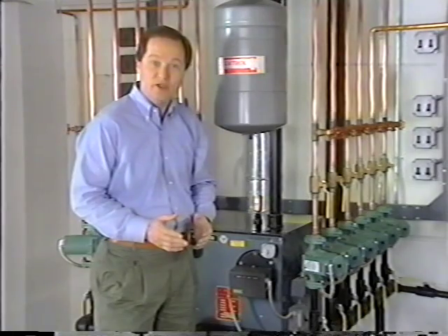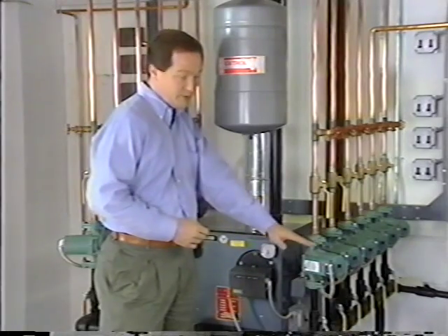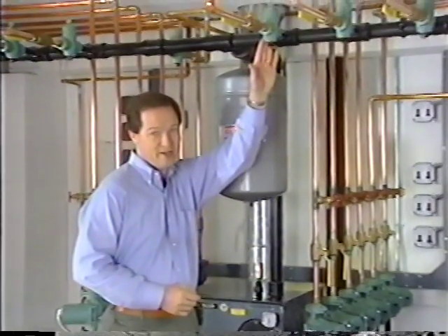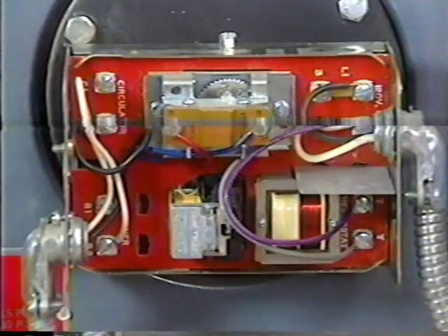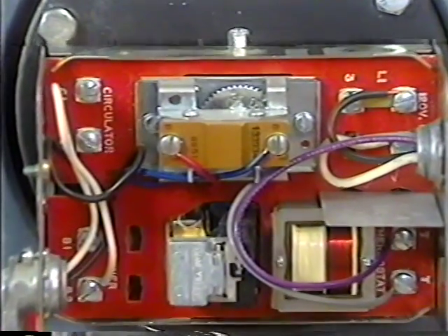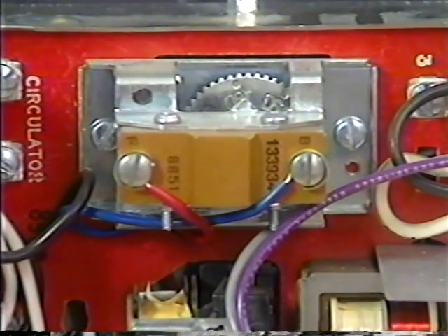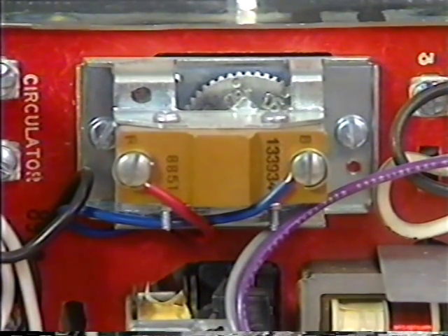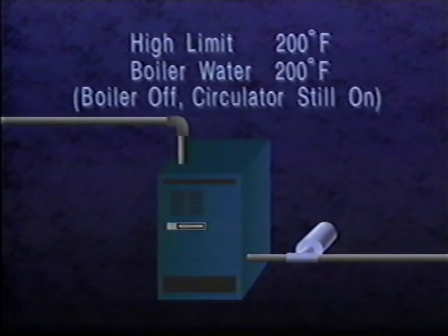For our discussion, we want you to be aware of how the following components work: limit controls, circulators, and flow control valves. Limit controls are thermally activated switches that are designed to react to changes in water temperature. Most limit controls have an adjustable high limit setting with a 10-degree fixed differential. The high limit setting is used as a temperature protection device for the boiler. If the boiler water should reach the high setting, the limit switch would cause the burner or burners to shut off and stop producing heat.